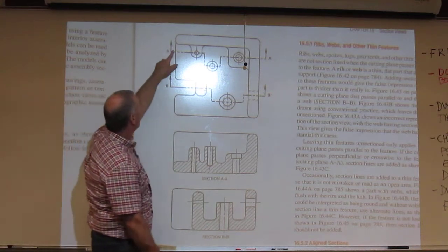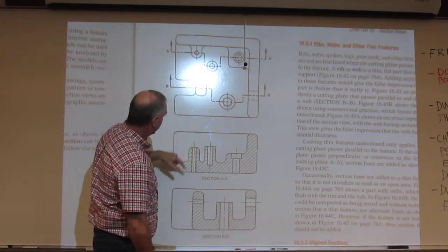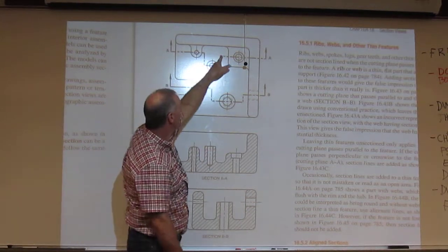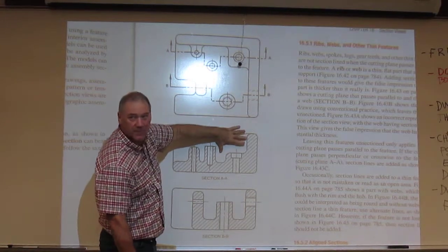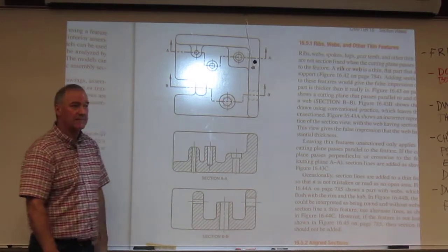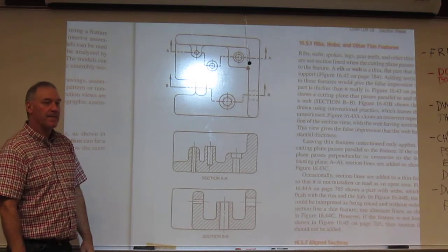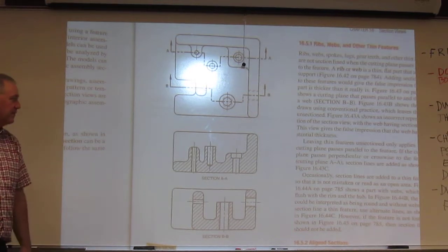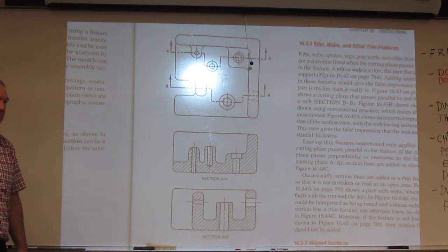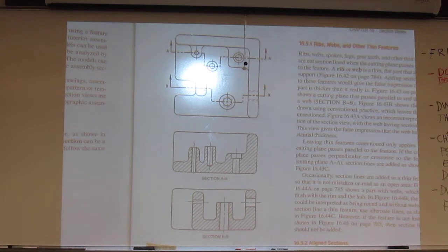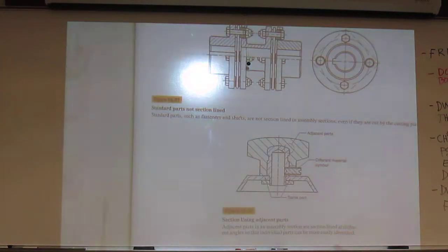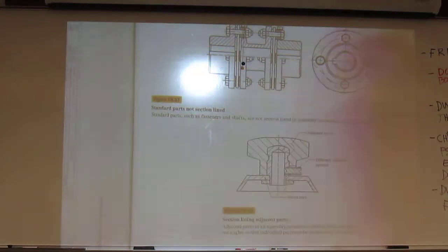So this one's right along that line. So from there to there is shown from here to here. From there to there is shown right there. There to there is shown from here over. And you're talking about just the way they're projected, not the way you determine what to cut. That is correct, the way they're projected. You project every view as if it's a standalone view. Any other questions on this one? Okay. Let's go to figure 16-46.